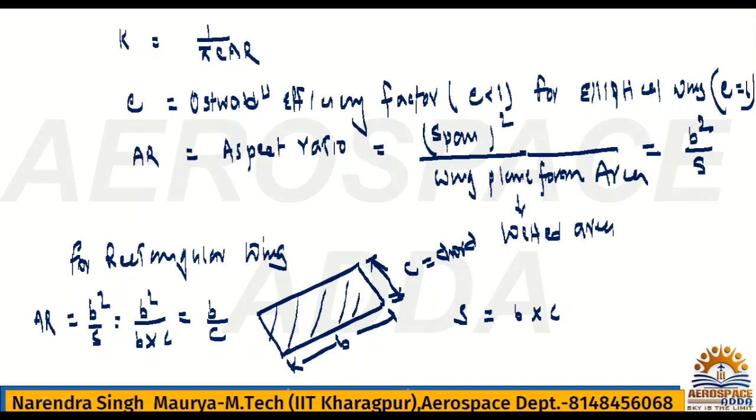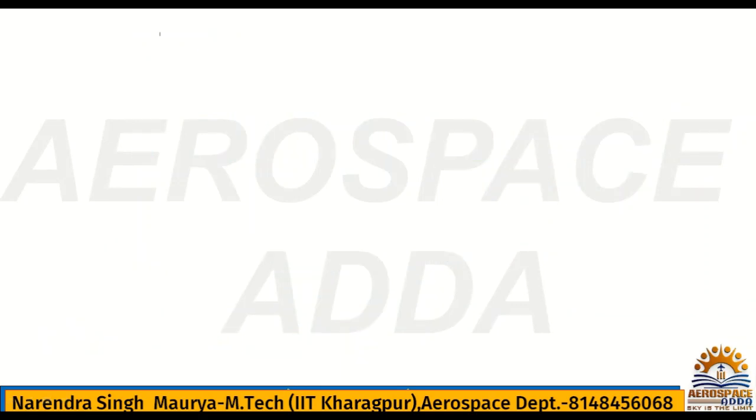Now we have one analysis, which is called the minimum drag condition. If you check for the aircraft, the condition should be minimum drag, because drag is the resistance. If the aircraft is moving, then the resistance force for the motion is drag. If drag is less, then resistance for the aircraft forward motion will be less, and obviously thrust required will be very less. Yes or no?